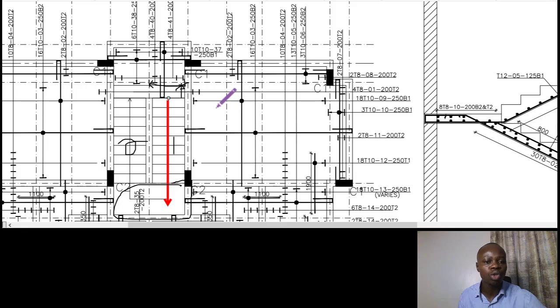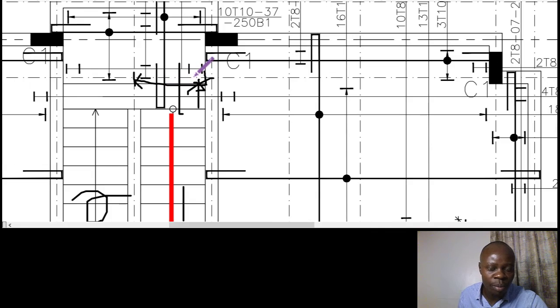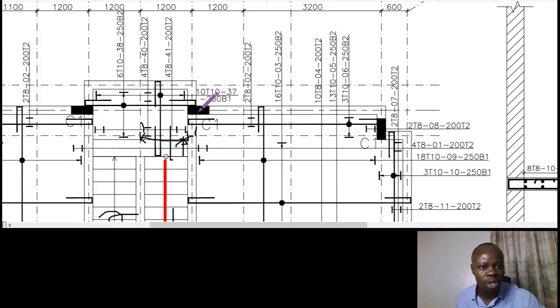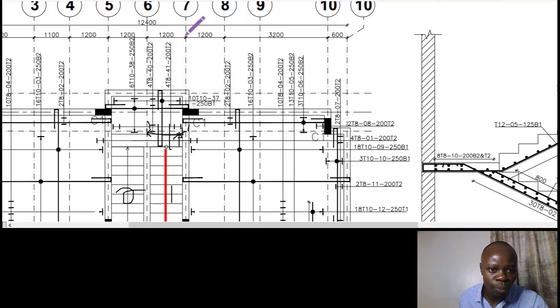Okay, so we need to know, and they have been cut across, to mean they have been cut in this manner, exactly where I've drawn my line. That is how the section has been drawn, but the bar is across it. So the length of the bar should be from this end point to the other end point. As usual, as the way we measured for the concrete, it's very important that you take that length from the extreme ends of the walls. In this case, this is showing you it's 1200.